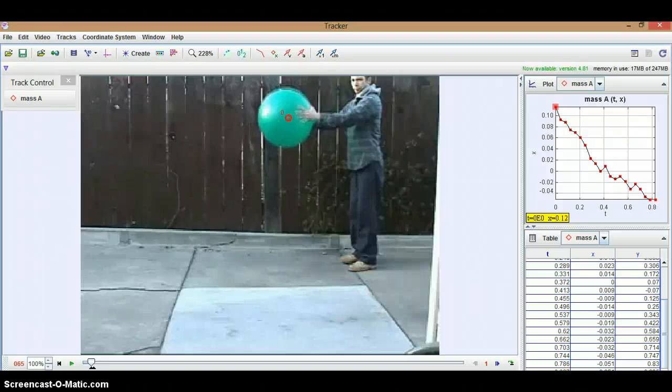The purpose of this lab is to model a ball which bounces on a surface. The model, using some estimations, will give us a contact force between the ground and the ball. We will be using both F equals ma to track the initial movement of the ball due to gravity, and F delta t equals m delta v, the momentum equation, to find the contact force.